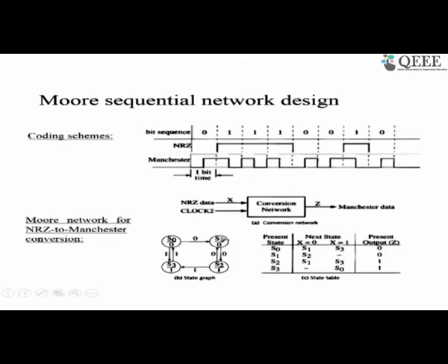So you go to a state where a 0 is produced followed by a state where a 1 is produced. Similarly in this state, when a bit 1 comes, there will be a 1 followed by a 1. We have to produce a 1 followed by a 0. So when a 1 followed by a 1 occurs, you go to a state where you produce a 1, then go to a state where you produce a 0.